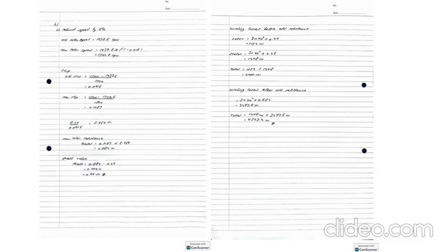Okay, we calculate the winding losses before adding resistance, for the rotor with the formula of 3 times 40 squared times 0.24. For the rotor, we got around 1152 watt, and the stator also uses the same formula, but with a different resistance, 0.26, and we got the answer around 1248 watt. And after calculating both the rotor and stator, we need to total the value. So 1152 plus 1248 watt. So before adding the resistance, we got around 2400 watt.